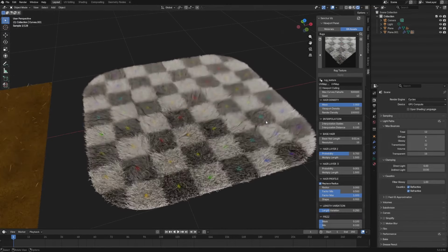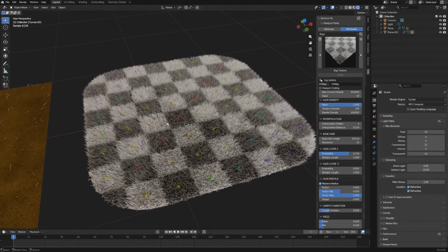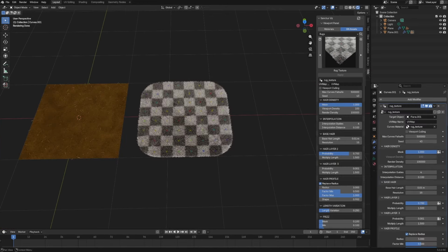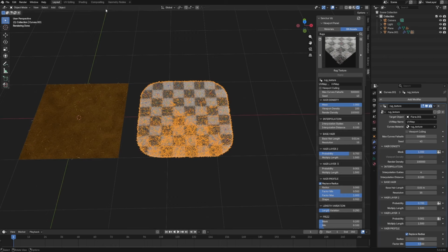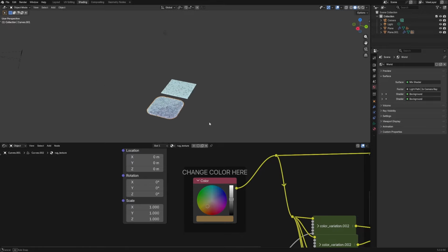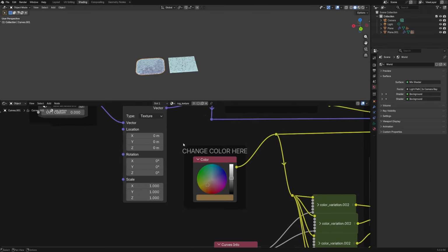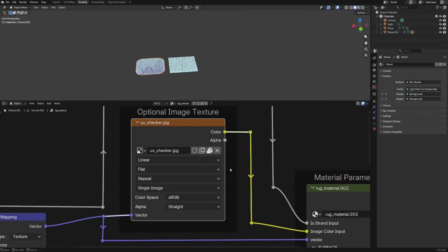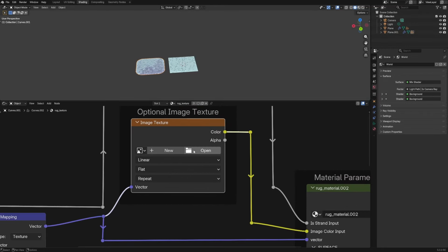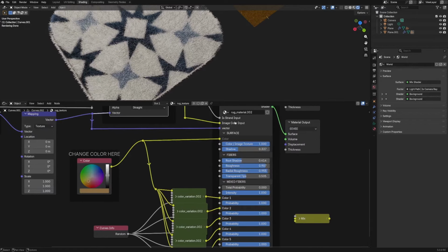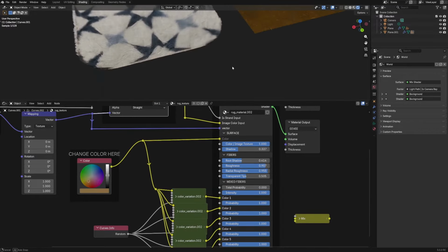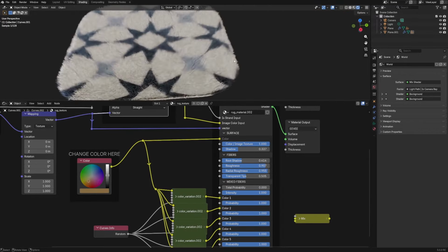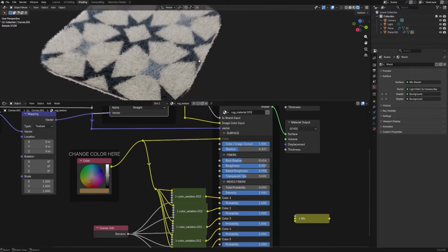And as you can see, in this case, we can use a texture, check the coarse material, rag texture. In this case, it's assigned also to the object, so you can go directly to shading, rag texture, and we replace the texture here. You can also change the more advanced parameters of the material here, but in general, with the default, you will be fine.